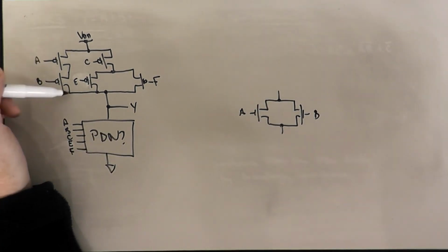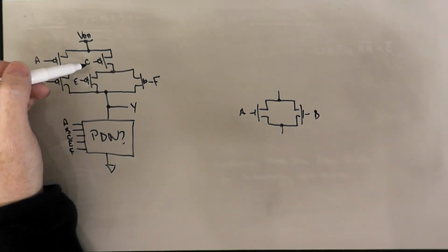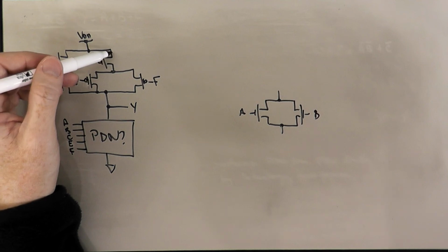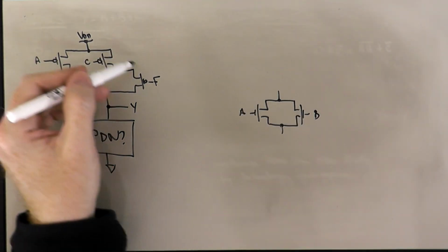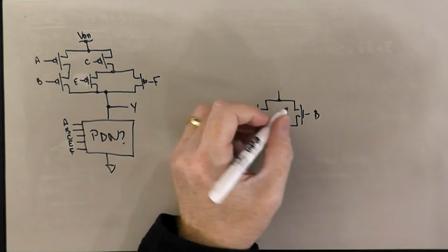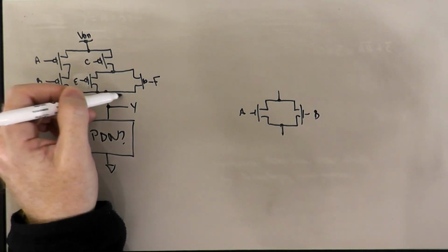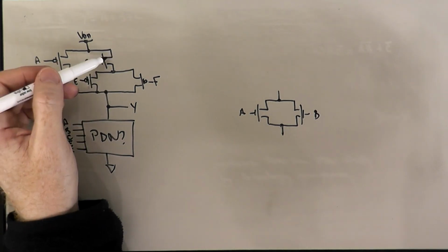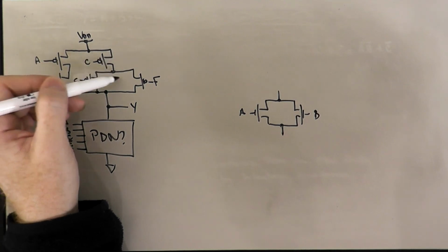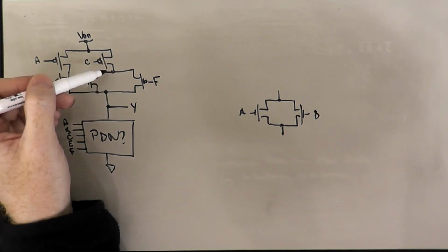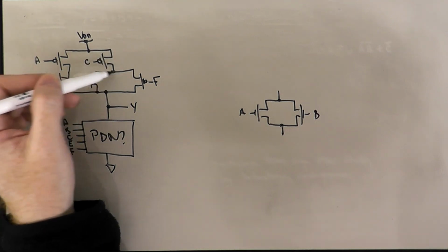Okay, that was in parallel with this thing. And so that's going to map into this piece being in series with the part that corresponds to this piece. So the piece that we have to design here is going to have itself two things in parallel, because we got the C thing in series with this subnetwork. So the C thing is going to be in parallel with the E and the F thing.